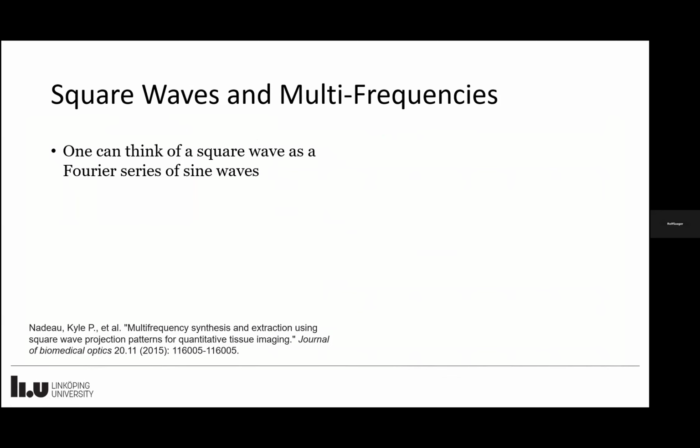But for the projection side, a standard digital micromirror device to project an 8-bit sinusoidal pattern takes about 9.5 milliseconds to just generate the dynamic range of that. So now with every single pattern, every single phase, it takes a long time. But if you have just a 1-bit projector, it's much faster because you don't have to have that bit depth anymore.